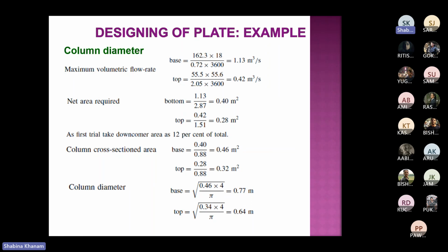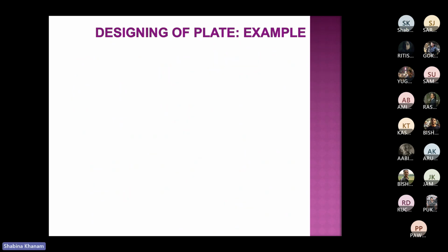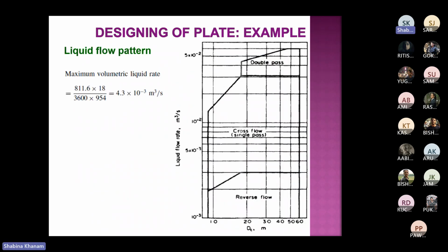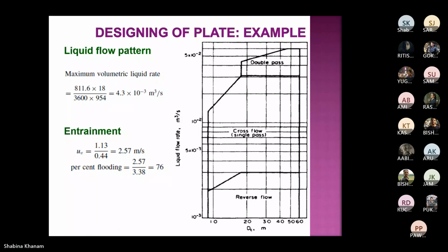If you are aware of standard diameters available in the market, otherwise whatever diameter you have obtained after calculation, you can consider as it is. But ideally it should be the diameter available in the market above this. Therefore 0.79 we have considered.